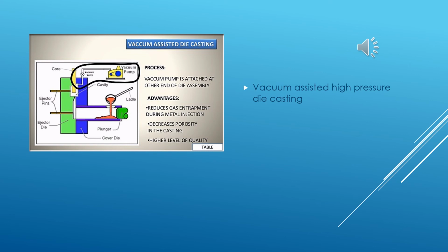Vacuum-assisted die casting offers benefits beyond simply reduced porosity. It also offers several technical advantages, like prevention of air entrapment, prevention of burning marks, prevention of shrink marks, increased surface quality, improved static, mechanical, and dynamic properties, and production of die casting parts for heat treatment.